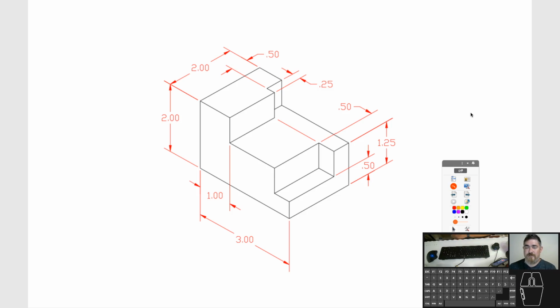All right, so now we have this one. A little bit more complicated. And so let's look at the design intent of it. Anything that's sticking out that's really design intent-y? There's one here, this face. There's no dimension for how wide it is or how wide this is, but it tells us that that lines up to this face. So that's the obvious piece of design intent from this: this face has to be lined up with this face.